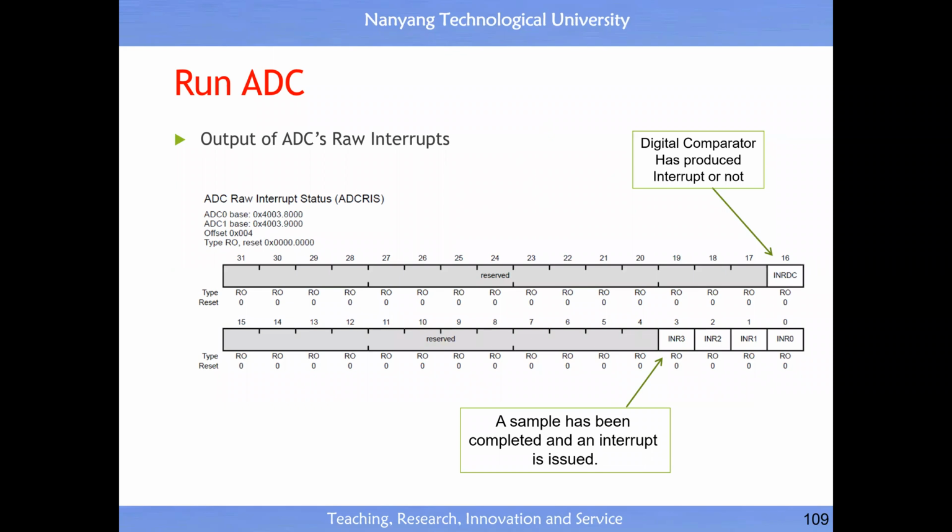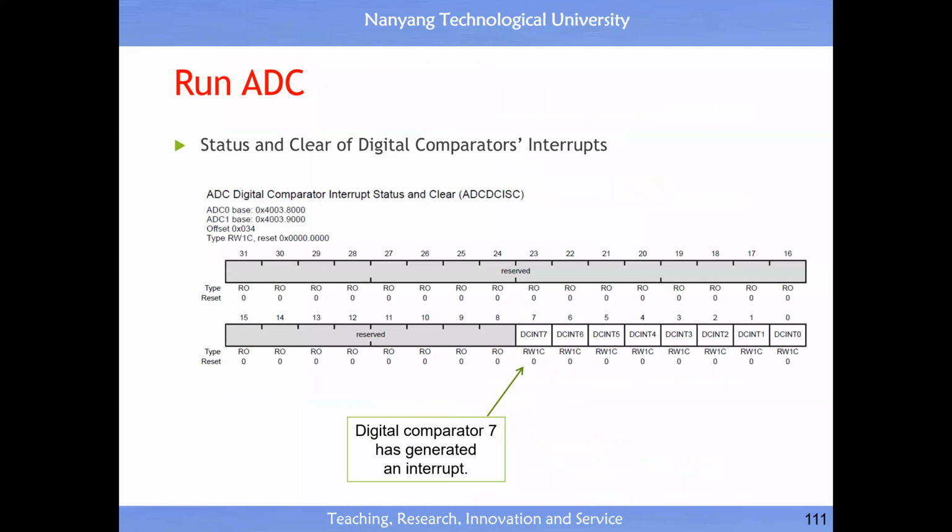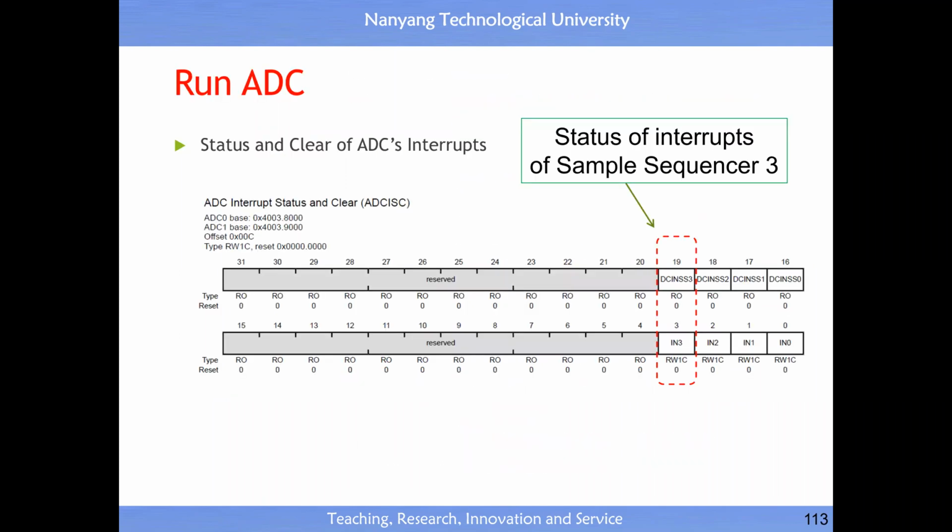Okay, so the hardware will also tell you once conversion is complete, and they will generate an interrupt signal. So your program can just wait. If this bit has been set to 1, then you just read out the data, done already. Always remember, once you make use of an interrupt to synchronize your operation, always remember to clear the interrupt. Last week I already told you that without clearing the interrupt, you may have a consequence, get some error, etc. This is to clear the interrupt.